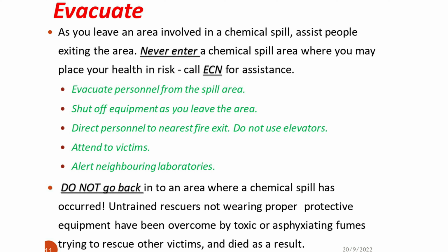Do not go back into an area where a chemical spill has occurred. Untrained rescuers not wearing proper protective equipment have been overcome by toxic or asphyxiating fumes trying to rescue other victims and died as a result.